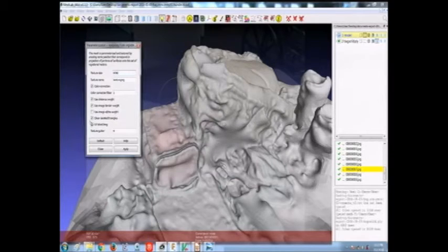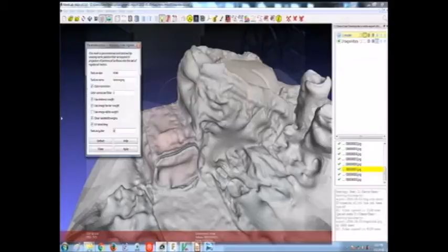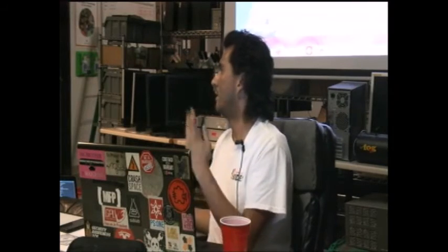I like to use UV stretching, and I turn off texture gutter, because what this is going to do is take the nominal, or the best colorization from each frame and apply the color. But by deleting this texture gutter, it's going to remove the seam in between each segment. So it works best by removing that texture gutter if you're trying to upload the result onto the internet using Sketchfab or whatever 3D imaging software you want.